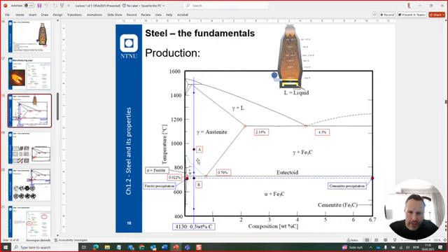If we go down to 800 degrees, we will have something called ferrite and austenite. These would be the two solids that the steel would form. When we pass this line called eutectoid, I'm not sure I'm very good at pronouncing it, typically here at something around 700 degrees, you will produce mostly ferrite, but you will also have something called cementite.